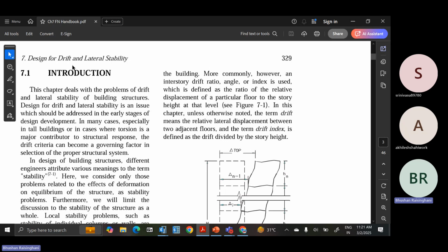Let's say there is a pinned connection at the bottom of the column and lateral load is applied. It will not have a double curvature. It will have single curvature only. And this will give us a total delta in the column. When the base is fixed, you will get double curvature. When the base is pinned, you will get a single curvature. And similar to that, you will get small P delta in the column and also the capital P delta in the column. So due to the increase in the gravity load and application of the lateral load, this is a sway frame.